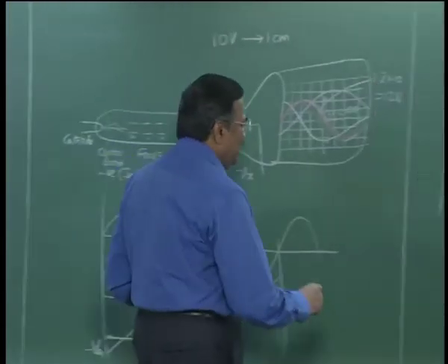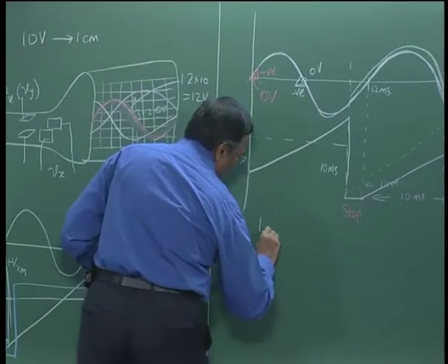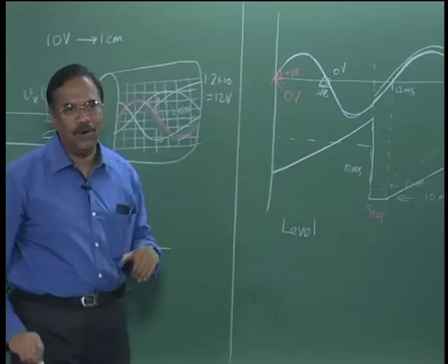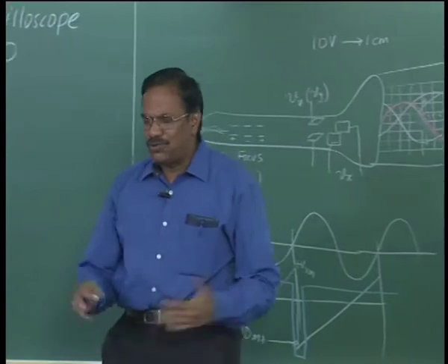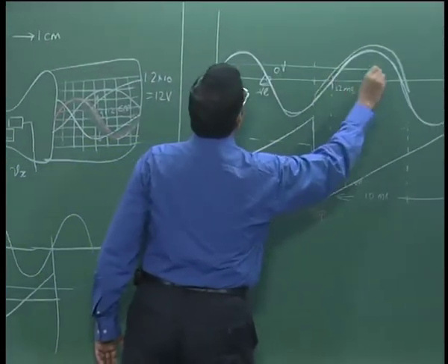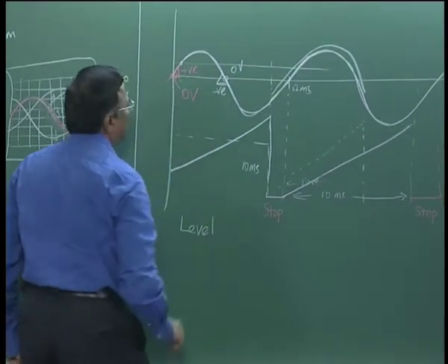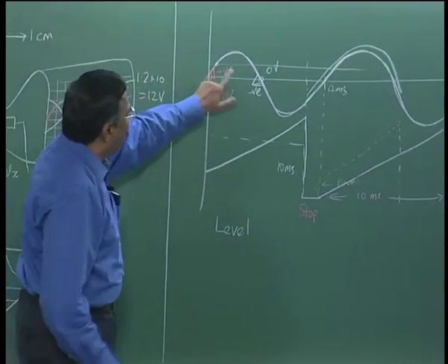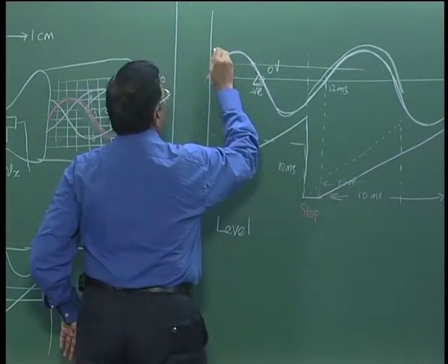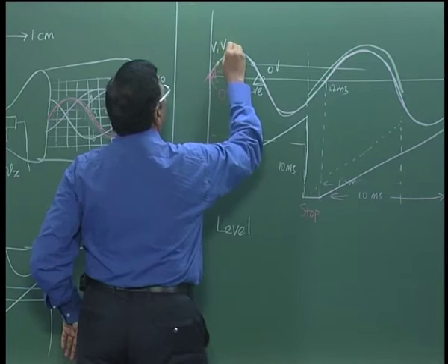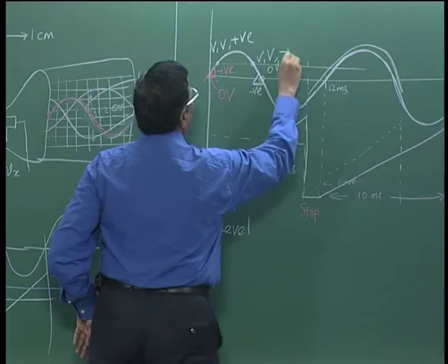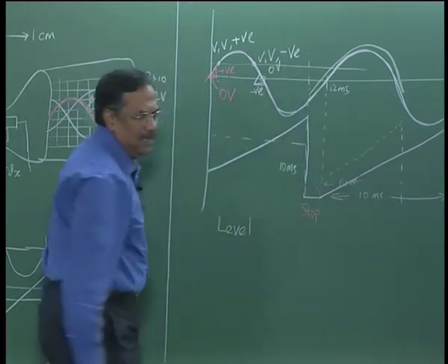I look at the level of the signal at that point, voltage level. I did not have to choose 0 volts, I can choose another voltage, right. I can say this is my starting point, right. Then I see there are two starting points. So, this is, let us say V1 volts comma positive slope, this is V1 volts comma negative slope, right.